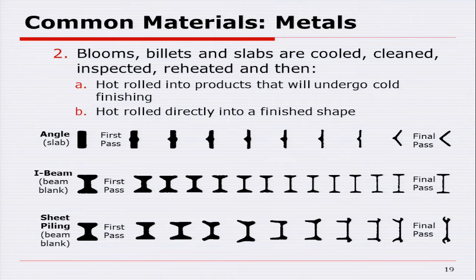We can push these whole things down into the ground. You get one stuck in the ground, you slide the other one right down into the ground, and you can hold back soil with it. You can also hold back water. We make what we call cofferdams, temporary dams that hold back water as we work inside of that piled off area.